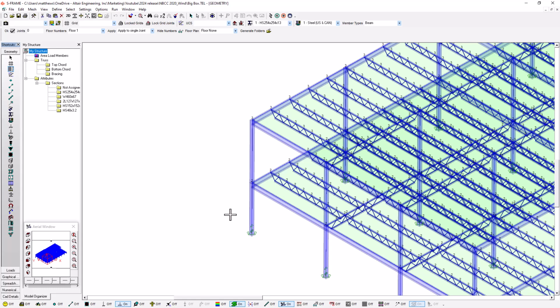In this case here, I have 3 stories, and you can see story number 1 is at the base. Maybe if I toggle off the display of my supports, we'll be able to see that a bit more clearly. Then I go story 2 above that, story 3, and so on. It's important that we have this to differentiate each story. We should start with story number 1 and work our way up in sequential order without any gaps.